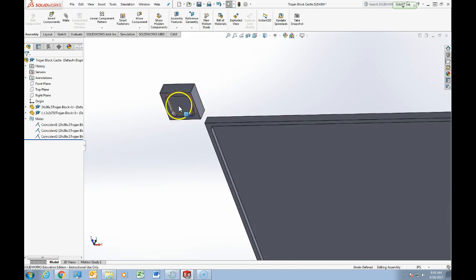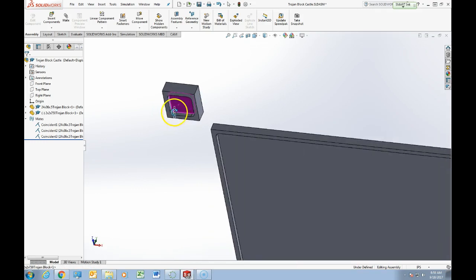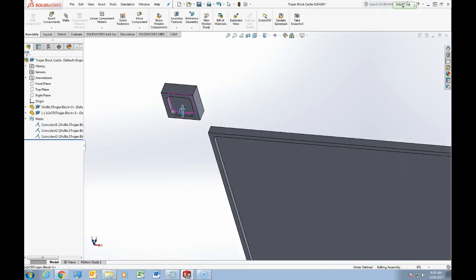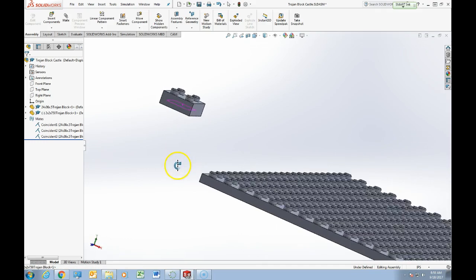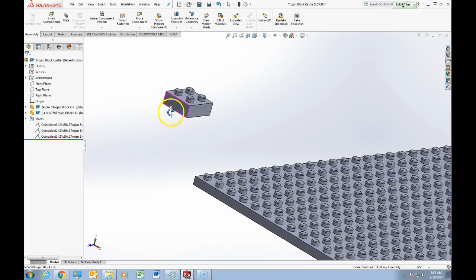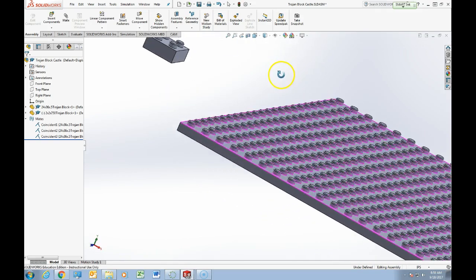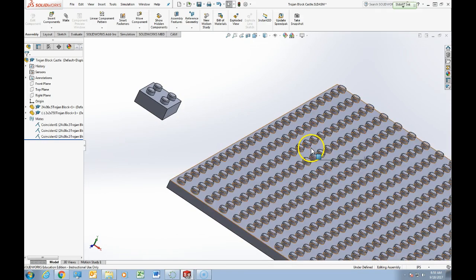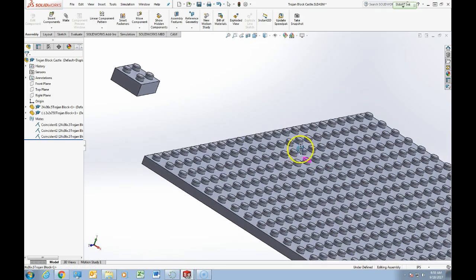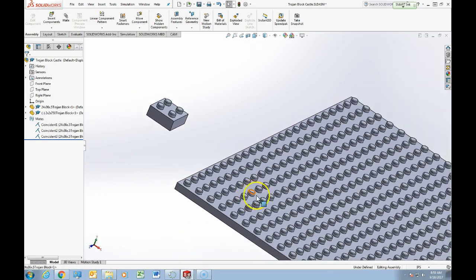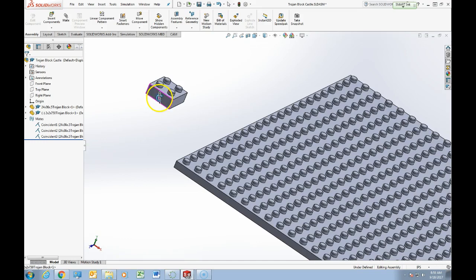And notice that if I orbit, I'm using my center mouse button, and I did a really funky orbit to give a little bit more control. I'm clicking and holding my center mouse button, but I'm having it focus on that one single part right here. Notice that it will actually orbit about that part. If you click anywhere else though, it's going to orbit around where your mouse is, which may or may not be what you really want. So if you actually click on a surface, it helps to keep things centered up. Now, oops, that's zooming in. I'm control panning around. So I'm going to orbit around this thing.